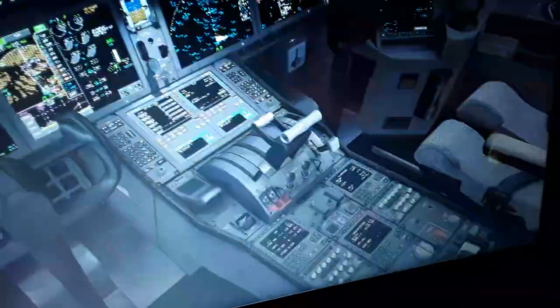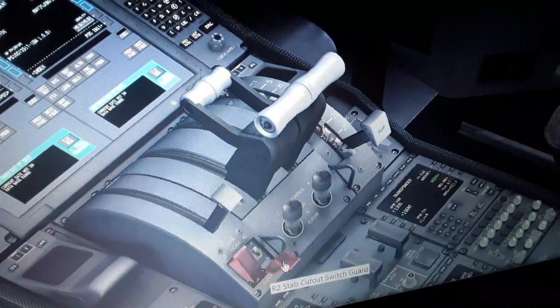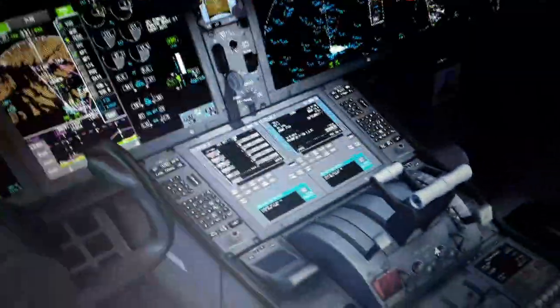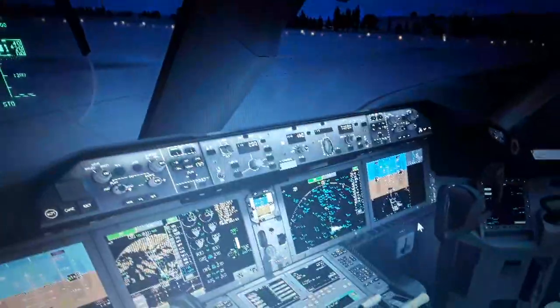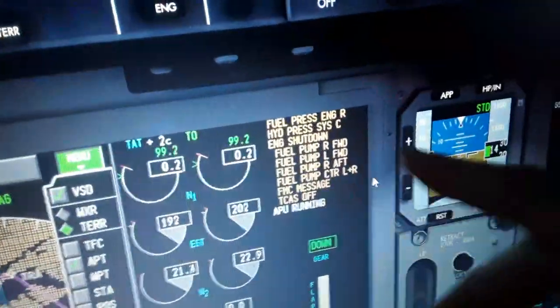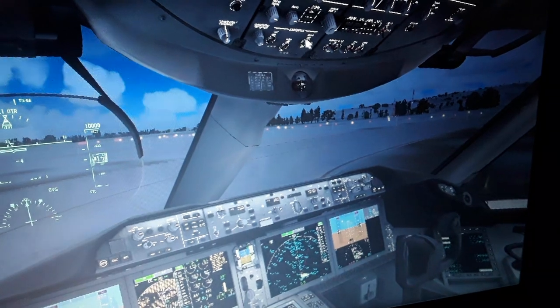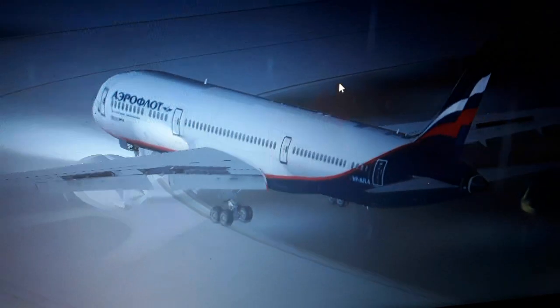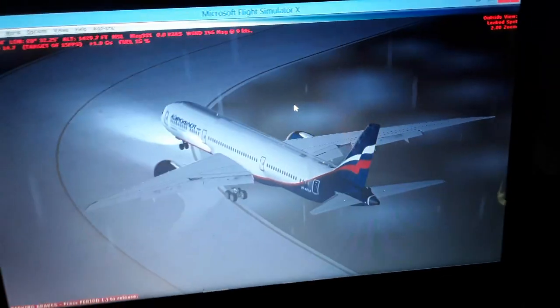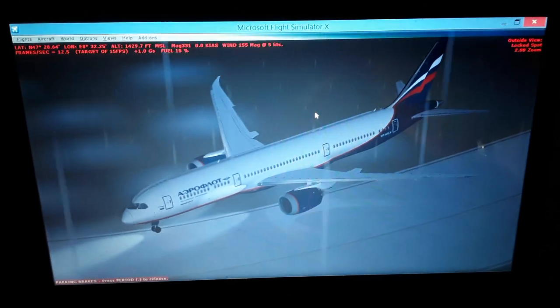We cannot turn off both engines and restart them very quickly. So we use the fuel control valves in the off position. Fuel in the off. You will see what it displays here: we have the failure, the shutdown of the engines, starvation of the fuel. So we go in here, we look outside. Also we turn on some lights. So we look outside, you can see the aircraft. The engines are off right now. We need to restart them very quickly.